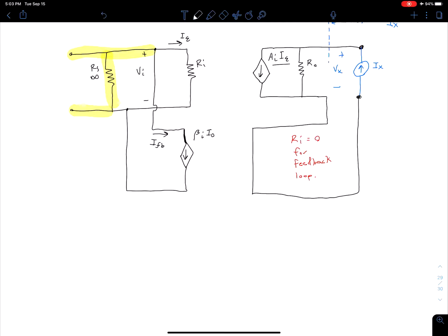We can see that I epsilon is equal to the negative of our feedback current. And what we see now is that instead of having an output current over here on the right, this is actually equal to beta I times Ix. Because our Ix current, so let me change colors, is of course flowing here, here, and then back up here to where we've defined it. So this is our Ix. So we can say this is equal to negative beta I times Ix.